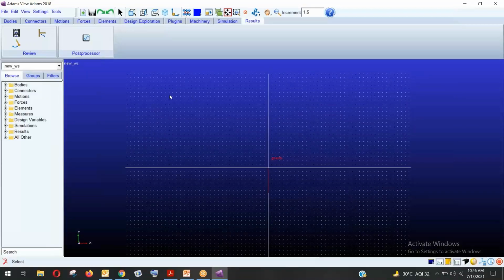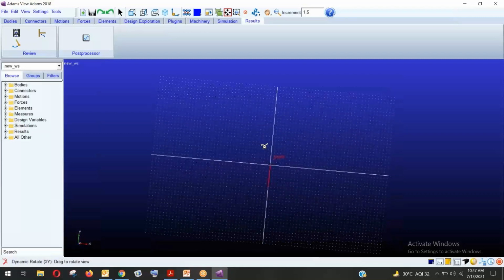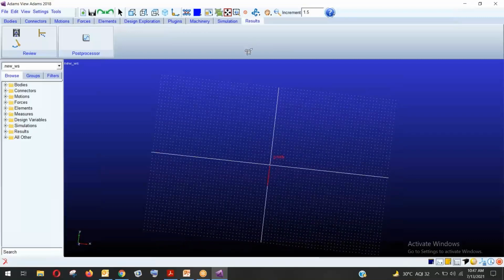With the help of the Z key, just by holding the Z key, you can zoom in or zoom out without clicking here. Or with the help of the R key, this is basically the shortcut. If you click on the R key, then you can rotate your model like this. Okay, so basically this is a quick tour and this is the model window.